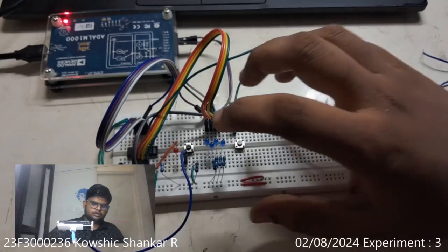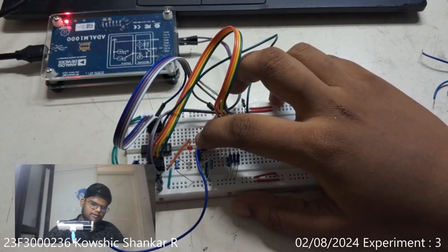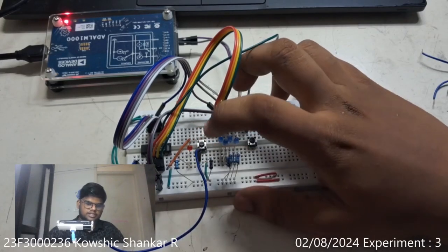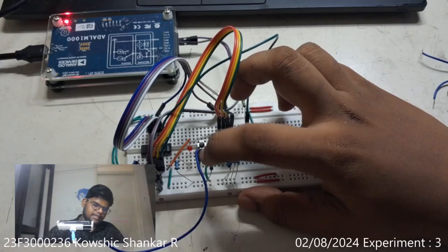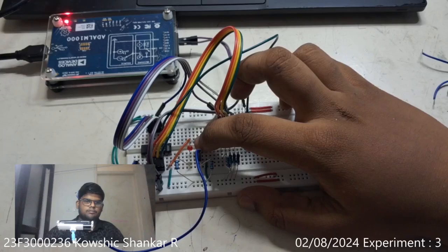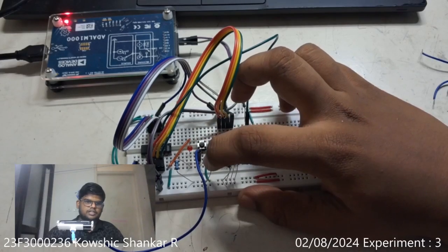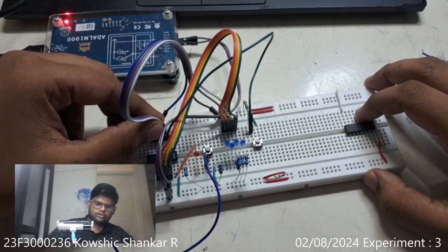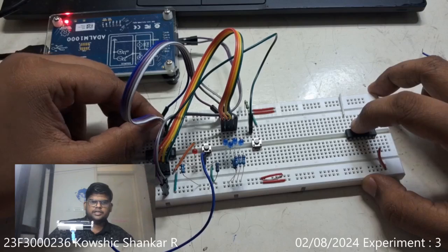I have disconnected the inverter from the circuit and I am going to explain how the load functionality works in the IC. To explain how the load works, I have connected a button which is active low in this case, by providing a resistor across it. It acts like a pull down resistor in this case. I have set the inputs A to D as the number 8.